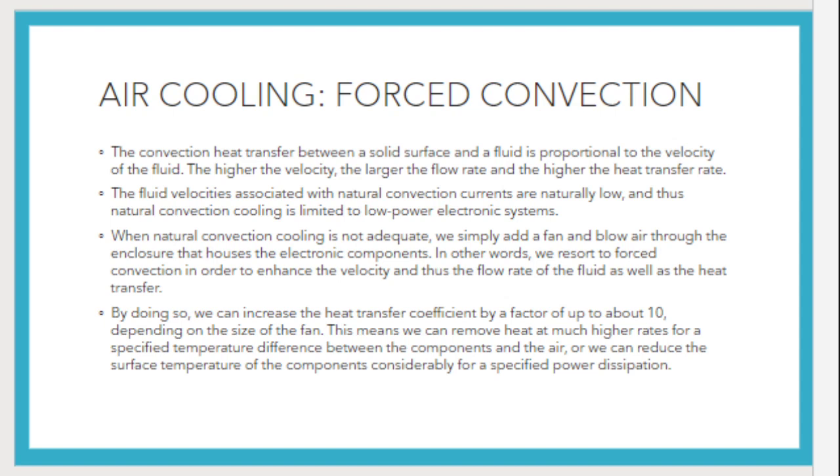The fluid velocities associated with natural convection currents are naturally low, and thus natural convection cooling is limited to low power electronic systems. When natural convection cooling is not adequate, we simply add a fan and blow air through the enclosure that houses the electronic components.